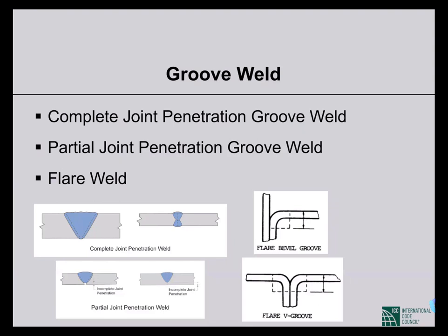And flare weld is when we have a situation where one plate is bent on another, or both the plates may be bent from both sides. Then at that joint, if we weld, that is flare weld. So these are different types of groove weld.